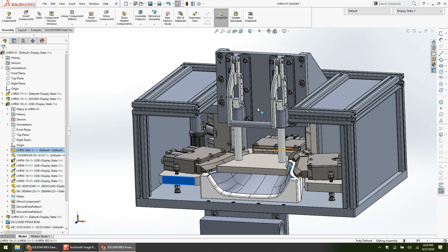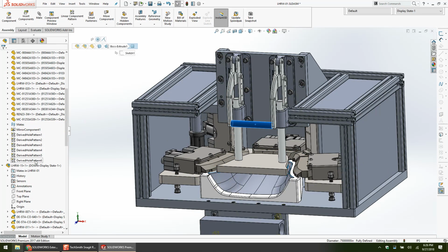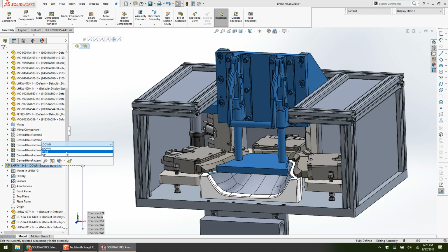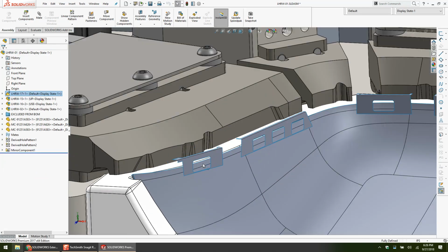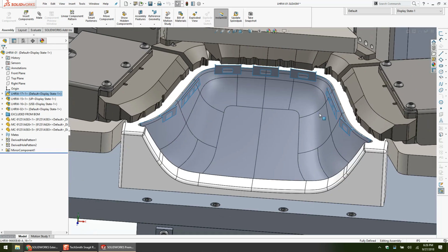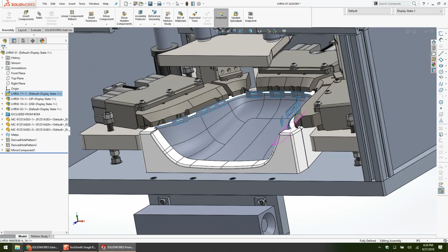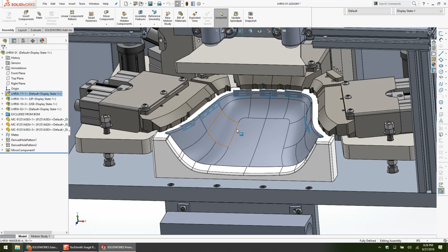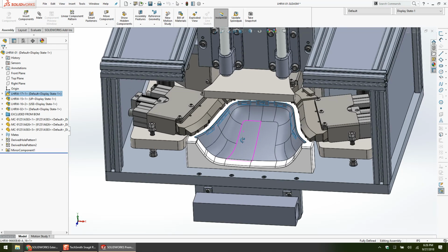And then these Destaco clamps here hold down. They come down and ride on all these windows of the part to make sure that they could hold the edges out to the side of the nest and hold it down appropriately so that the slides can come over and edge wrap. So pretty simple concept. Who's ever designed an edge wrap machine knows they're a ton of fun, and even more fun to tune and tweak. So maybe I like them.